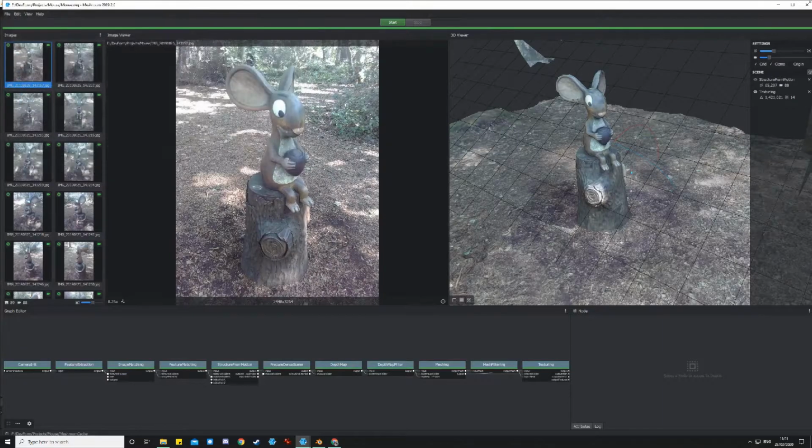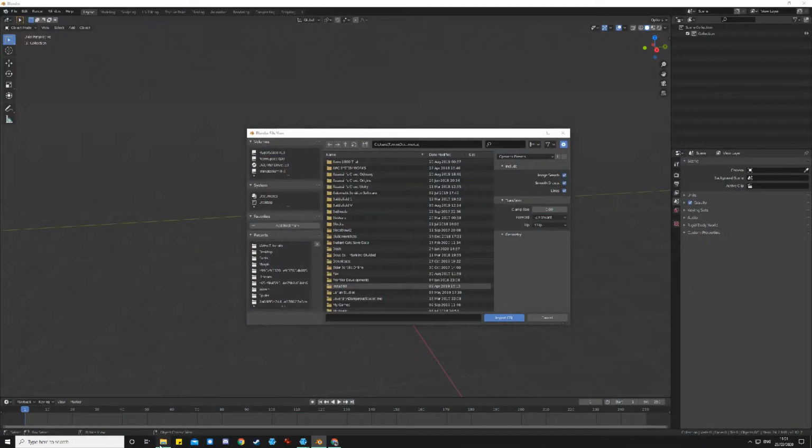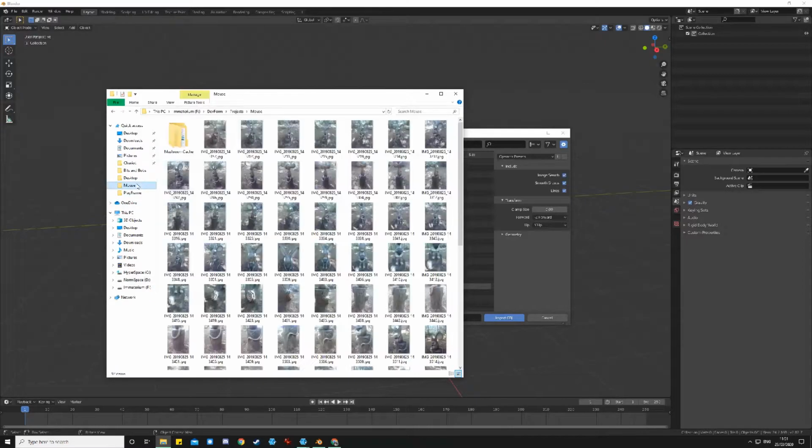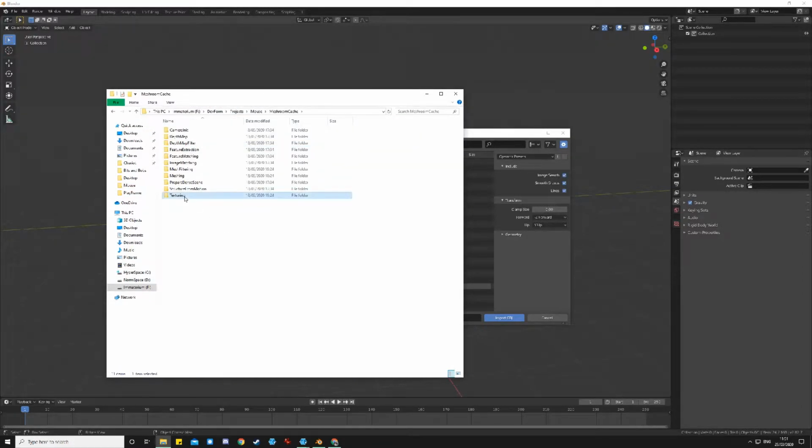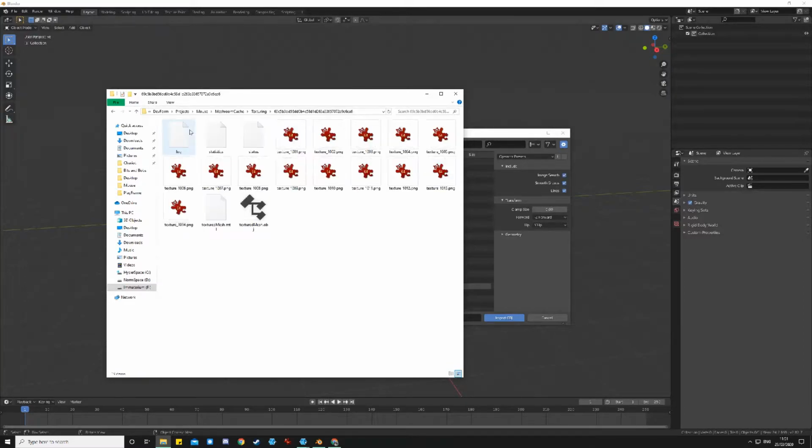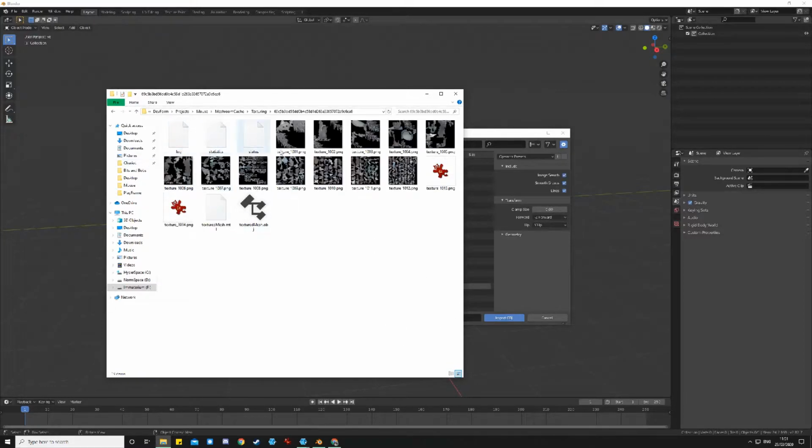Now, you can't see it in there because we're just using a different folder thing, but if I just use Explorer now to take us to mouse, and MeshroomCache, texturing, in the folder with the long name, and there we are. And so we've got a lot of data in here. We have loads of PNGs, which are the actual textures, picture files that they use to color the images, and then you've got a textured mesh .mtl and a textured mesh .obj.